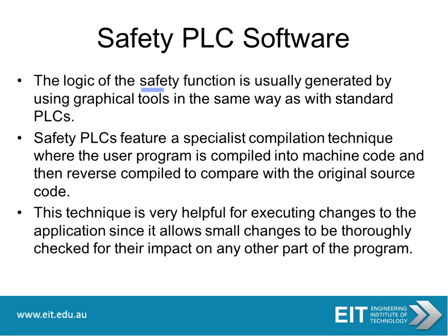Now the logic of the safety function is usually generated by using graphical tools the same way as with a standard PLC. Safety PLCs feature a specialist compilation technique where your user program is compiled into machine code and then reverse compiled to compare with the original source code. This technique is very helpful for executing changes to the application because it allows small changes to be thoroughly checked for the impact on any other part of the program.